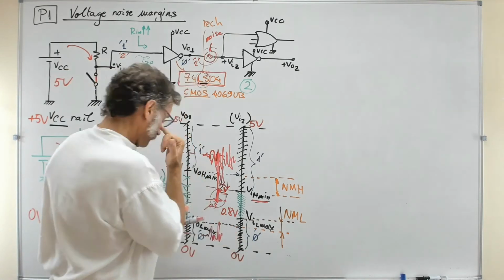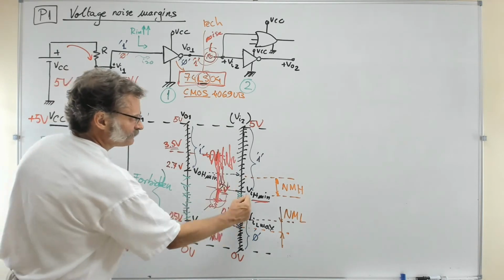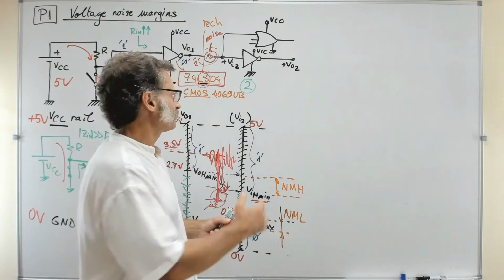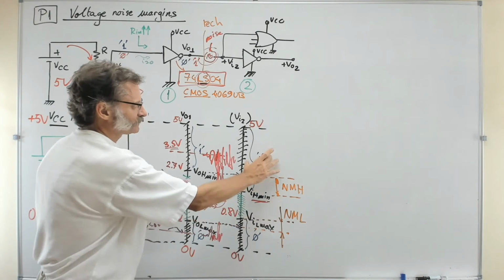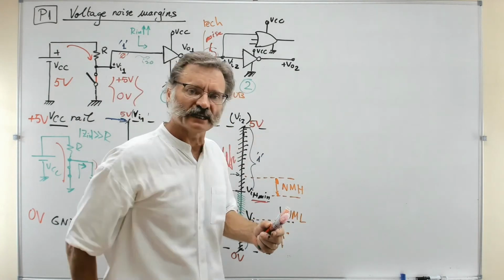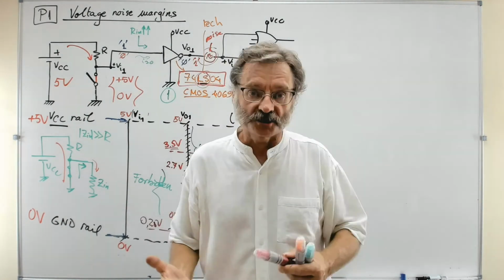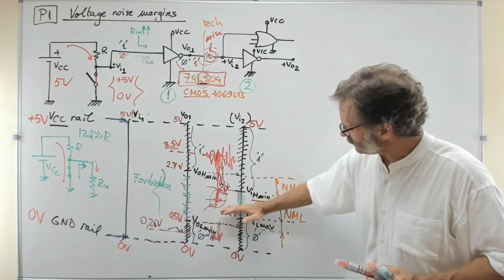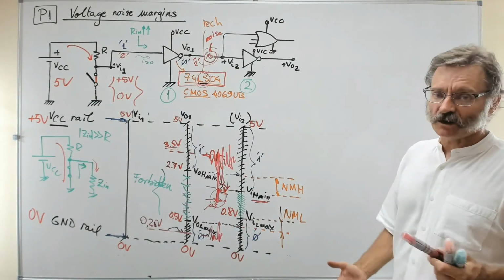So, well, for all this time, while the signal is below the VIH minimum, you have a problem, because you know the real voltage that you are applying to this gate is under, I insist on this, is under what is understood as a 1. So it is clearly in the forbidden zone, so you will never know what is going to be the output. So now imagine that here you have processing circuits. What is what you are going to process? There is no way to know it, because here no one knows what kind of logic. So the circuit may go wrong.